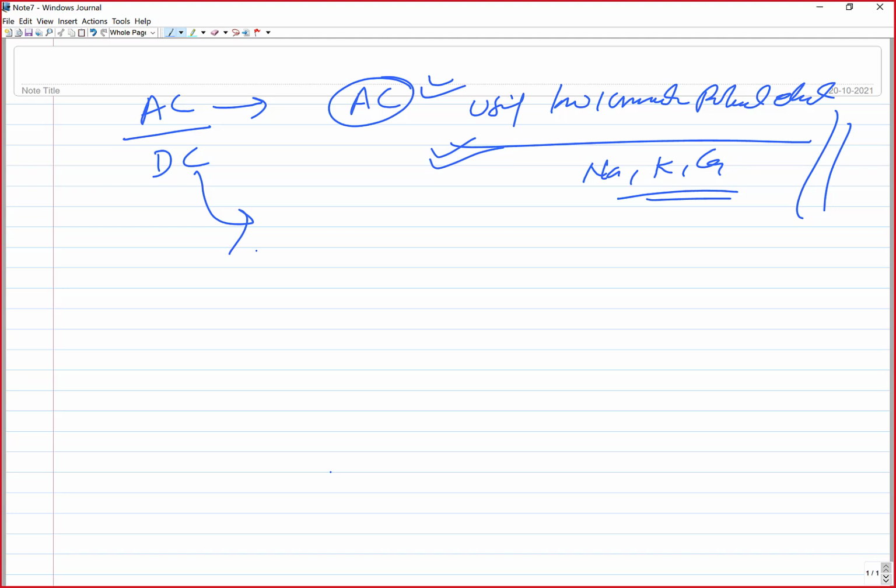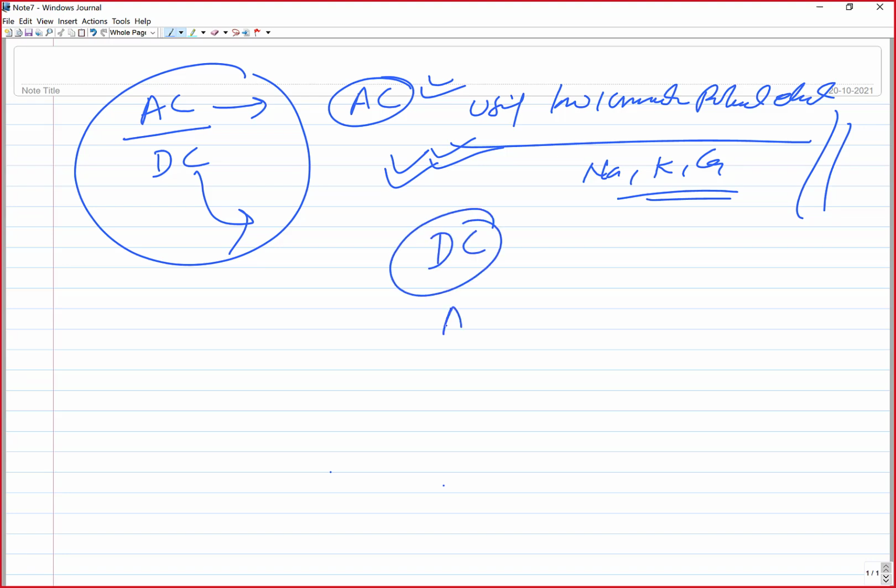So we have to consider what kind of composition and coatings the given electrode has, and based on that we decide if we can use AC or DC. Normally, manufacturers recommend which type of electrode it is and what it can be used with.